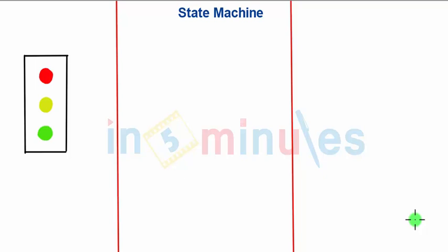To understand a state machine, which is nothing but a sequential circuit: up till now we have seen the counter as a sequential circuit. A counter counts the states. It has to retain its state till it is hit by the next clock cycle. Now see, there is a clock cycle which turns from state 1 to state 2 or to different states. But a state machine is a different kind of sequential circuit.